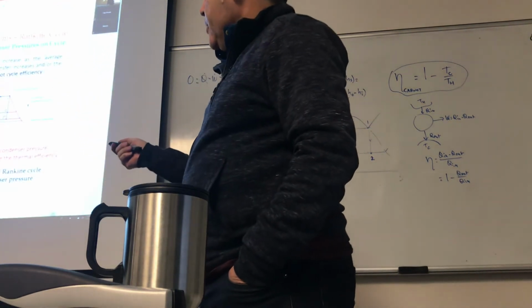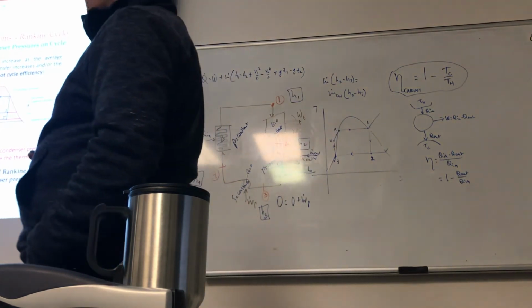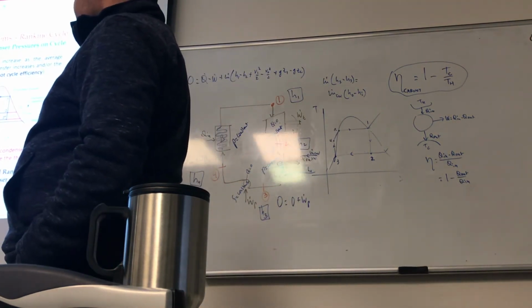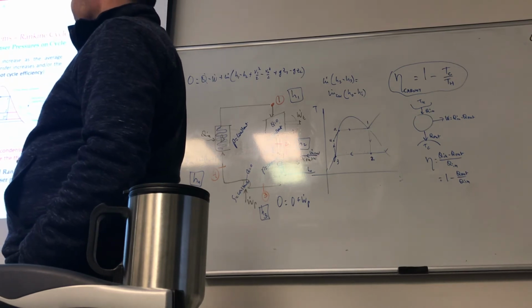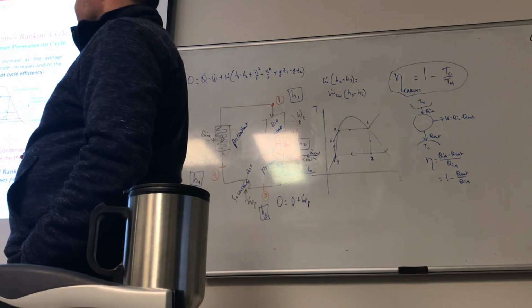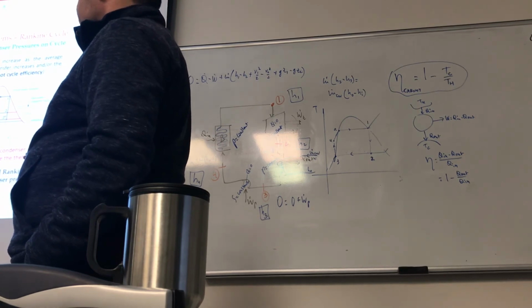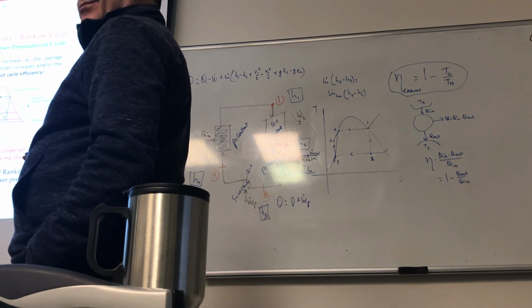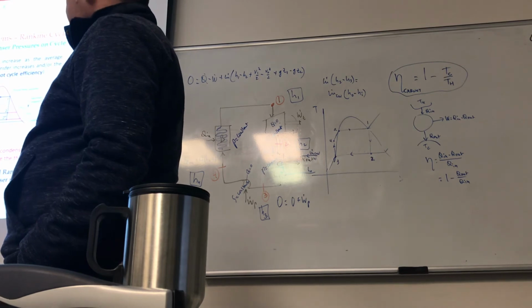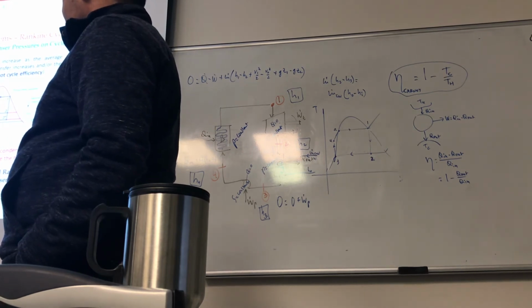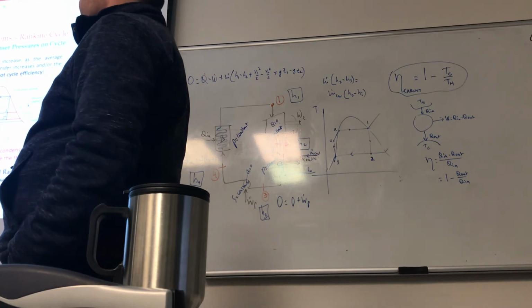So if you increase the pressure of the boiler, graphically speaking, this is the original state, 1, 2, 3, 4, 1. Do you all see this? Now, if I increase the pressure, then my starting point goes where? Saturated vapor has to shift to 1 prime, right? Now I go 1 prime, 2 prime, 3, 4 prime, 1 prime like this.